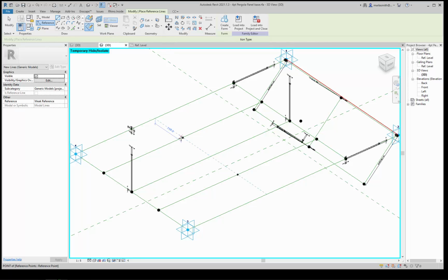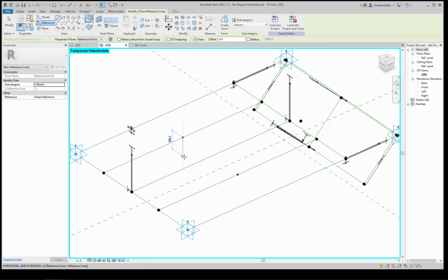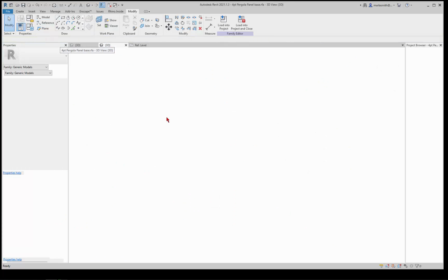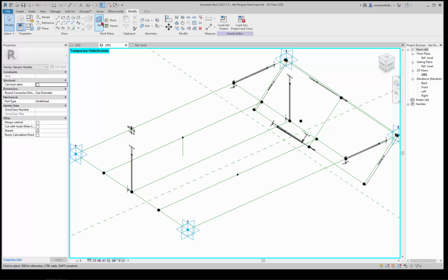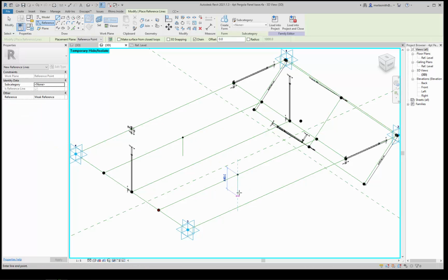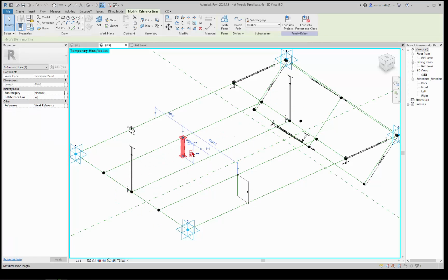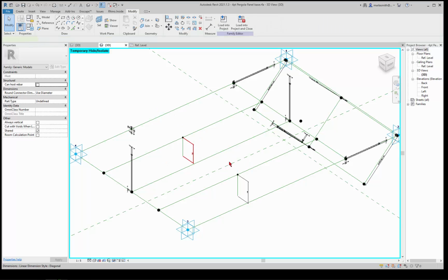Make sure 3D snapping is off so it will stay on that little point, right? And I think, is that right? It doesn't go down, does it? Just want to look at this guy. Yeah, so that guy goes down, and then we'll go set here and draw a reference line there, straight down. Then I'm just going to pick this and make that current, pick this and make that current by clicking on the dimension string, so you don't have to do the dimensions.